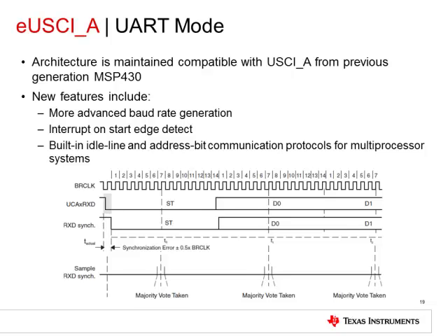configurable 7 or 8-bit data with odd, even, or no parity, independent transmit and receive shift registers that can be read from or written to using DMA, built-in idle line and address bit communication protocols for multiprocessor systems, receiver start edge detection for auto wake up from LPM modes, programmable baud rate with modulation for fractional baud rate support, and independent interrupt capability for receive, transmit, start bit received, and transmit complete events.